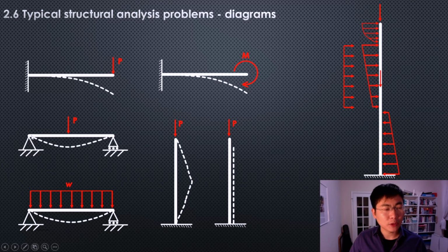The other way is a typical beam where you have the force happening in the middle. Sometimes the force, the concentrated force or the point force will happen at one side or another side. Then this picture on the bottom, it shows a distributed load is applying on this beam member. So that's a very common practice as well. For example, your roof will have main structural beams handling the load. And if we look at the roof plate, it will create a distributed load on the beam members.